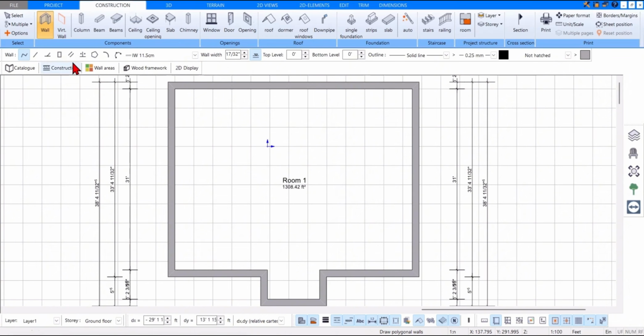I select the function Draw Wall Parallel to Reference Line. This function helps you draw a wall exactly parallel to an existing wall edge at a very specific distance. First, I click on a wall edge that the new interior wall will be parallel to. Afterwards, I'll enter the exact distance, that is, how far the inner wall must start from this edge. Then I click the starting point of the inner wall, directly enter the desired length, and confirm with the Enter key. That completes the inner wall.